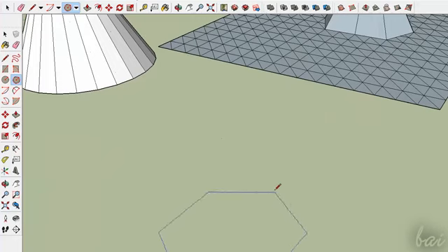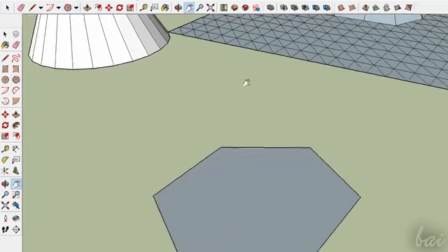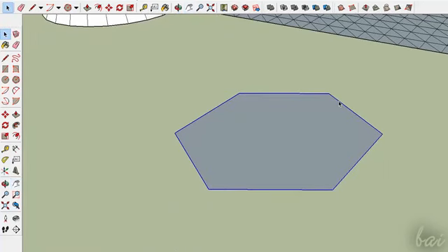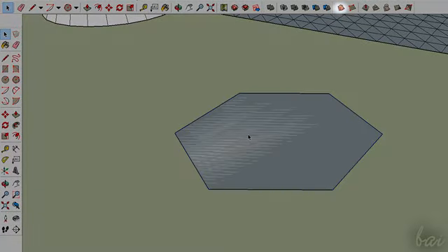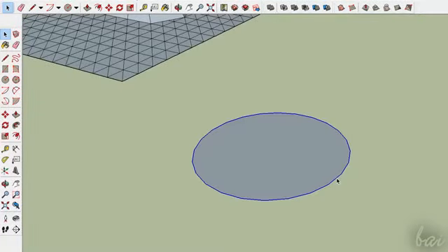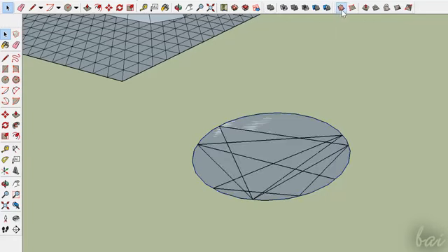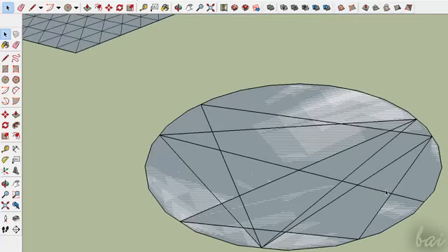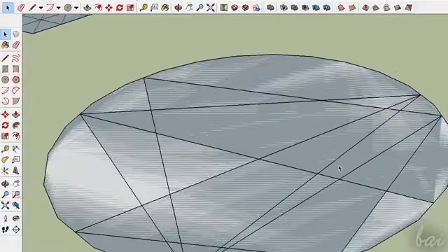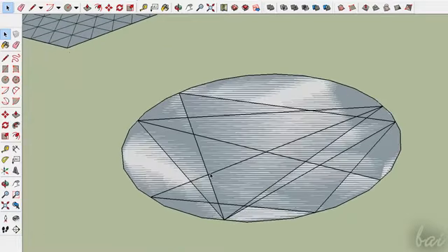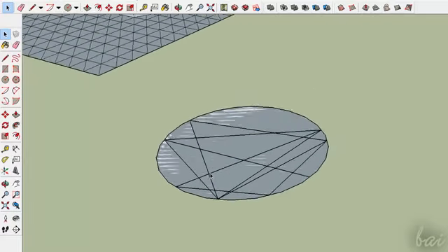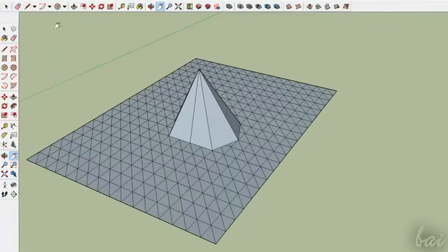You can also create a mesh from a defined contour. Select first the contour from which to create the mesh and click create from contours on top. The mesh object works fine as long as you use simple shapes, like rectangles or polygons. If you use circles or arcs, you may need to be more careful on the tools you use. When your complex shape is done, you may need to convert it to a normal object.